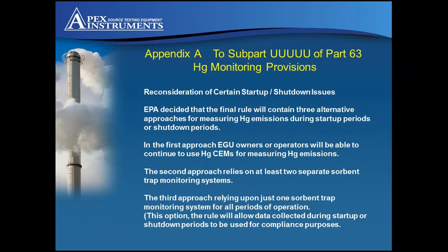Appendix A tells us 720 hours before a RATA must be performed and passed. 720 hours or 30 days. Not a great deal of time to perhaps get your primary system repaired and back in use, or more importantly, to organise a RATA test for the replacement equipment.